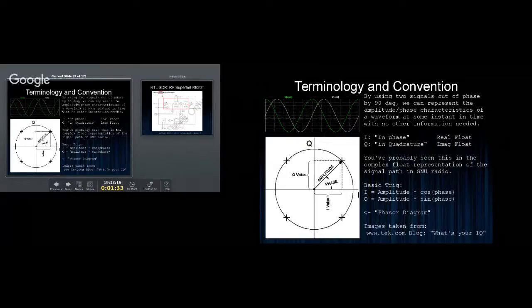What's important about quadrature is that we can use simply the magnitude of both of these signals to reconstruct a phasor. A phasor has magnitude or amplitude and phase. One of the problems with digitization is that analog to digital converters only convert magnitude. So you lose the phase information. This is quite important on the digitization aspect of software-defined radio, but I've got more of a hardware kink, so that's where I'll be approaching this discussion from.